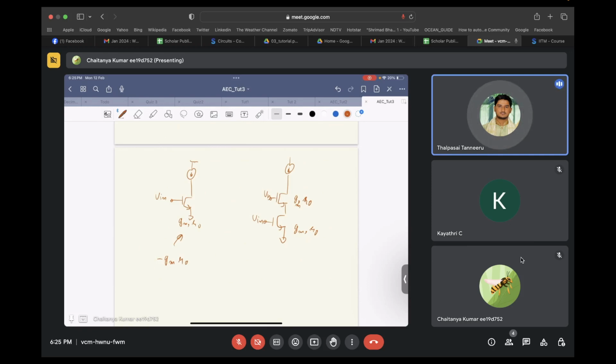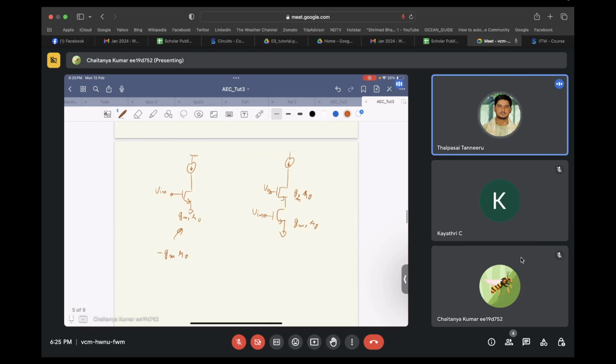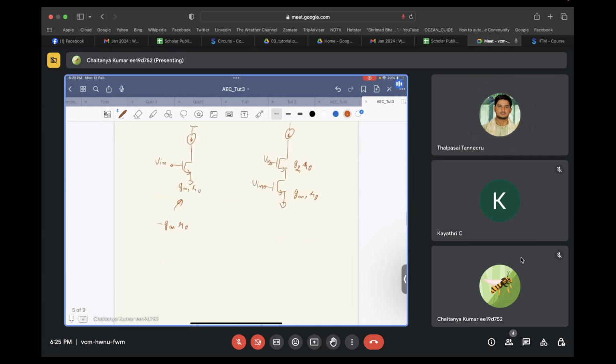In small signal analysis, the current source will be open circuit, and the drain to source channel and ro will be parallel to the drain to source terminal. So this is basically the small signal equivalent. It's basically like this.